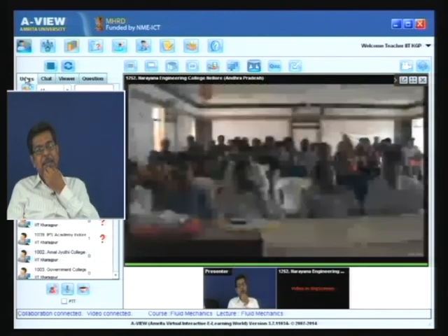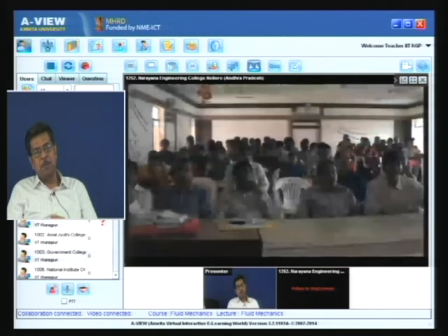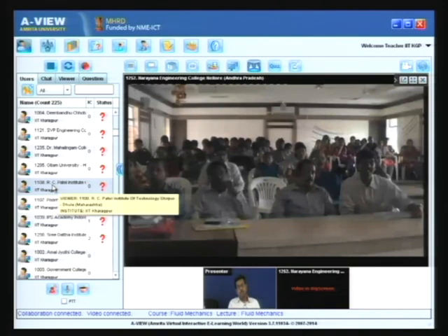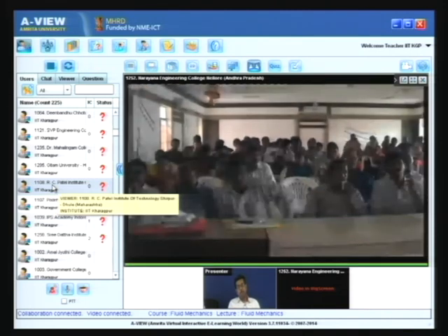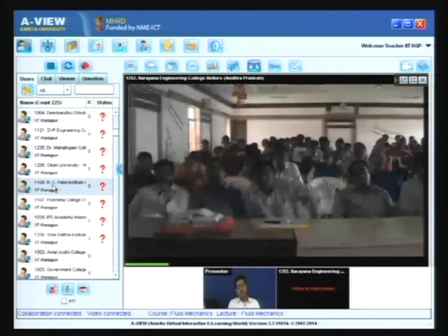We have already given an example of lawn sprinklers today. So lawn sprinkler is one example. Therefore, the conservation of angular momentum principle can apply to those systems which have an angular momentum change and have a rotation, where torque or moments are applied by virtue of which there is a rotation, or by virtue of the rotation due to the flow of the fluid or the change in the angular momentum of the fluid, the moment is developed.